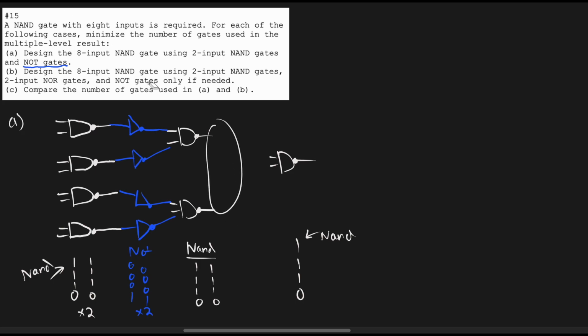And so to connect them, what we're going to do is we are going to have a NOT gate right here, and we're going to have a NOT gate right here. So these will connect to this output, or this input, sorry, and then we can write a little truth table here. We have NOT, and now we're going to be looking at this. These are our inputs, and so the output would be 0, 0, 0, 1.